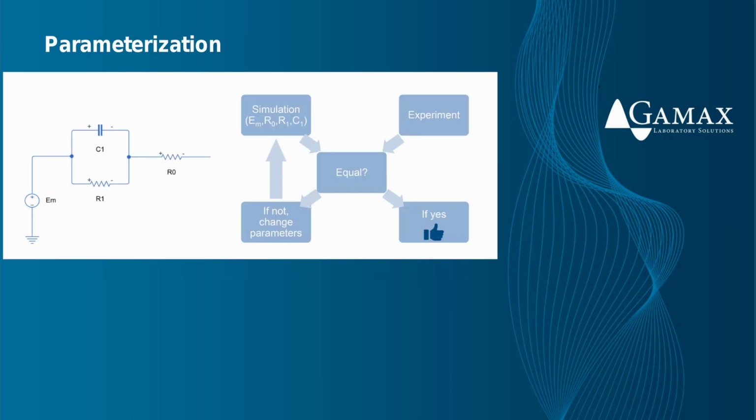As far as the parameterization is concerned, it is crucial to capture the electrochemical and dissipative phenomena observed when testing a real battery, as well as their dependencies on states and environmental conditions. These requirements demand the use of matrices instead of scalar parameters, functioning as lookup tables and reflecting the physical behavior of the lithium-ion chemistry. One possible way to determine the characteristic parameters of an equivalent circuit is performing parameter estimation.